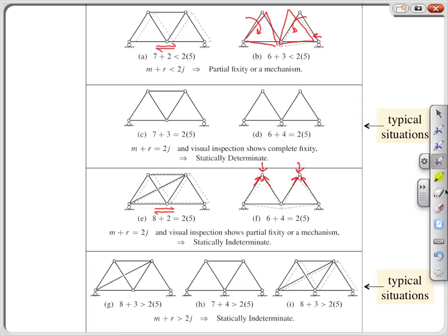Analysis of the bottom center joint then indicates equilibrium is impossible unless the bottom members undergo significant rotation and accompanying deformation, so that the orientation of those bottom members is sufficiently changed that they can counteract in tension the compressive loads brought into the joint from above.